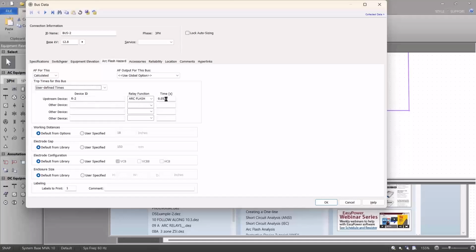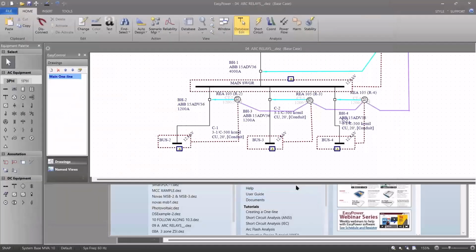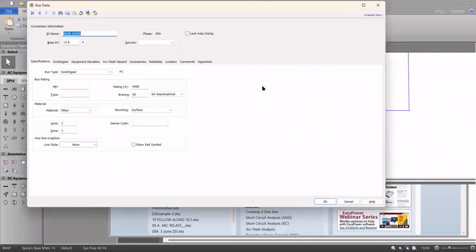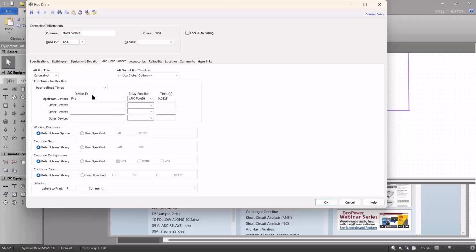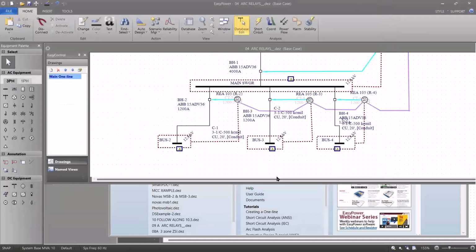This is a fixed time that the manufacturer, with some amount of buffering, would support as far as the response time of the relay plus the opening time of the breaker. Does that make sense? Each bus would have that setting, and it may vary based upon where the system is and where the breaker opening time is, but it will give us an idea of the isolation that could be counted on